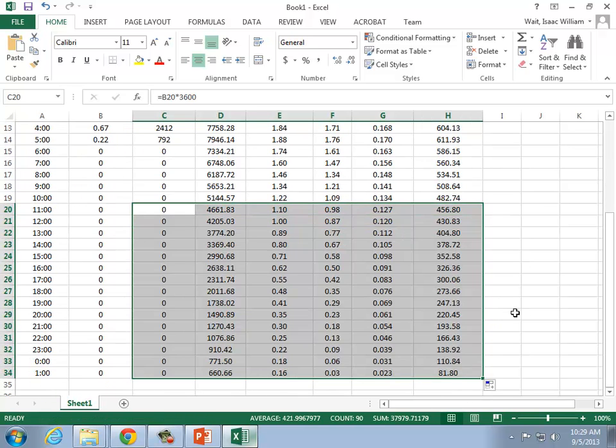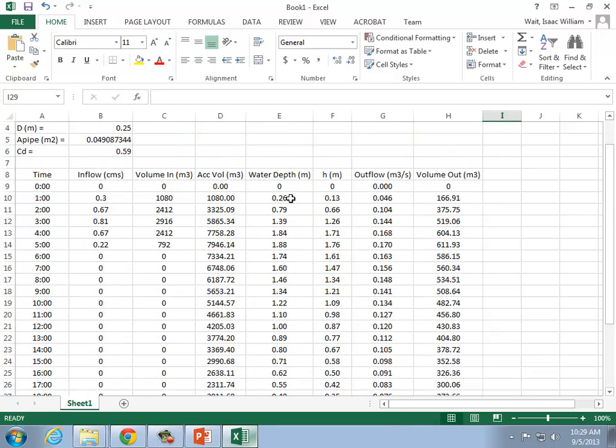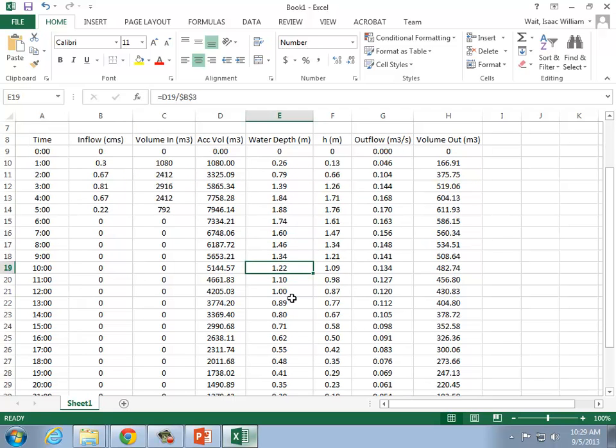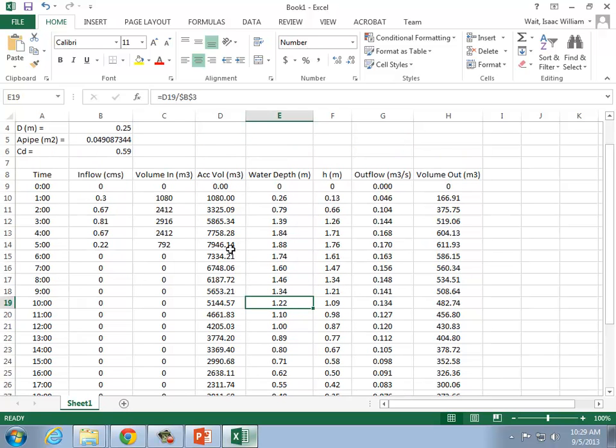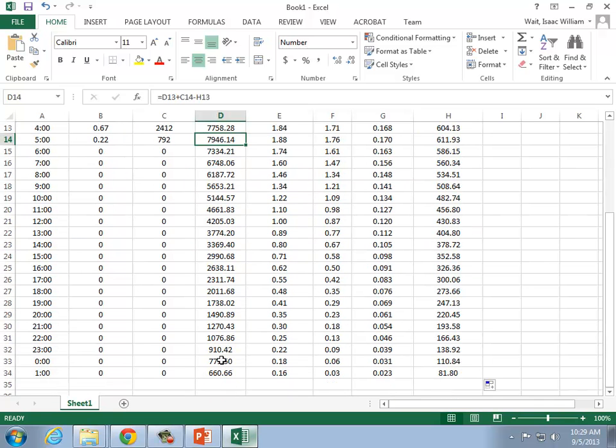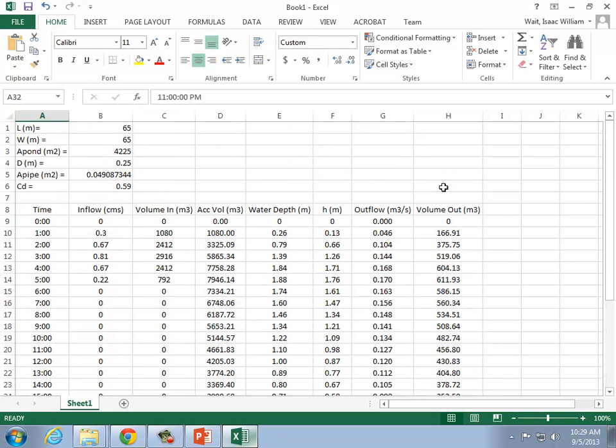The pond will continue to drain. If you look, the water depth goes up, and then it's going to be declining. We want to find out when the water level in the pond is approximately 800 cubic meters, because that's 10% of what was there at the peak. It's down to about 800 cubic meters sometime between hour 23 and hour 24. All right. Any questions about this example?